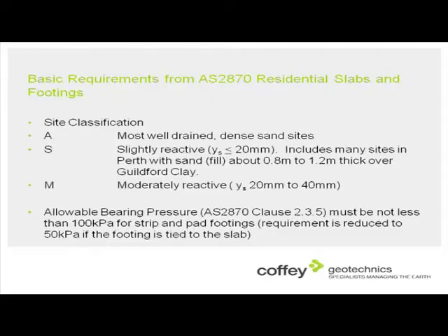Okay, so I'm going to be talking about the effects of sand fill and groundwater on foundations for residential buildings. The basic requirements for the footings for a residential building come from an Australian standard, AS 2870, Residential Slabs and Footings, and it works on a system of what's called site classification, where sites are classified according to the expected amount of soil movement from shrink and swell of clays.